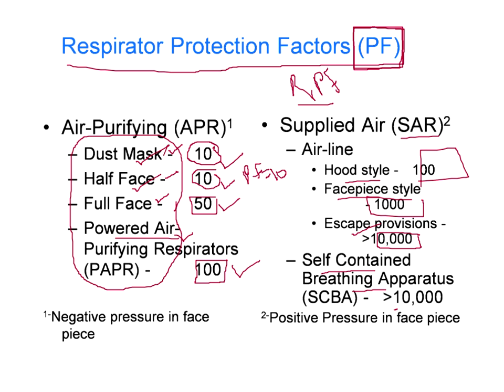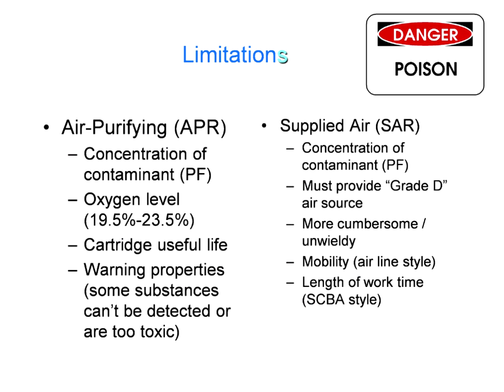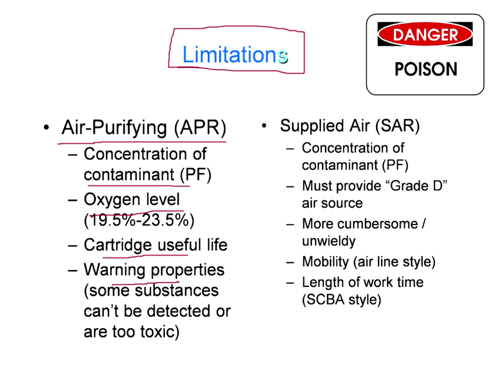So we have to follow these standards, because these standards have been found by medical examinations. Keep in mind the protection factors for supplied air. If it is 100, use hood style. If it is 1000, use face piece style. If it is more than 10,000, use escape provision styles. If it is more than 10,000, you can also use self-contained breathing apparatus. Please keep these things in mind.